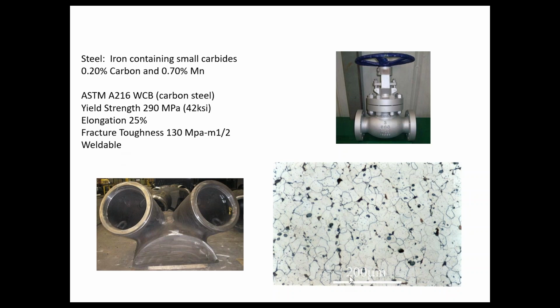This micrograph is the same size, and you can see these little black specks. These little black specks are not graphite. They are mixtures of steel and carbide, and they strengthen the alloy. So that's what makes it stronger. And so this material is just like the material you'd buy if you bought steel from a steel supplier, except it's cast instead of rolled.